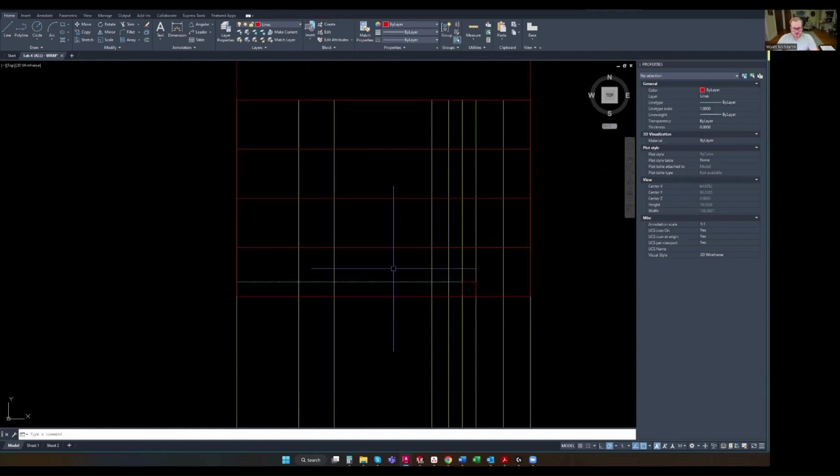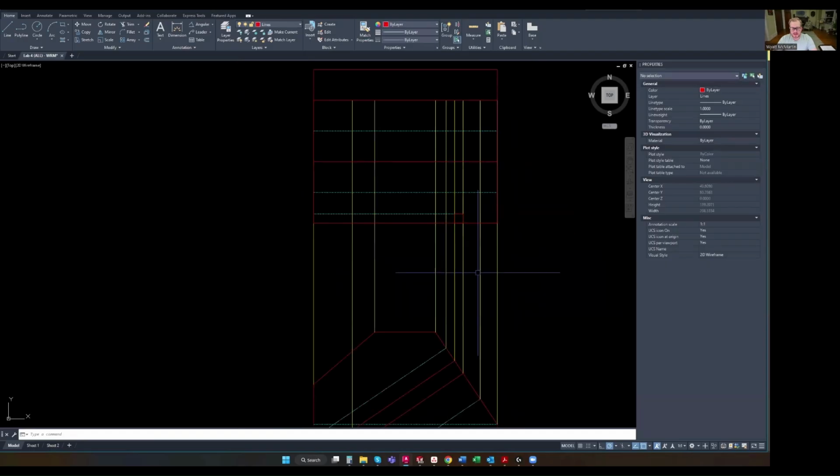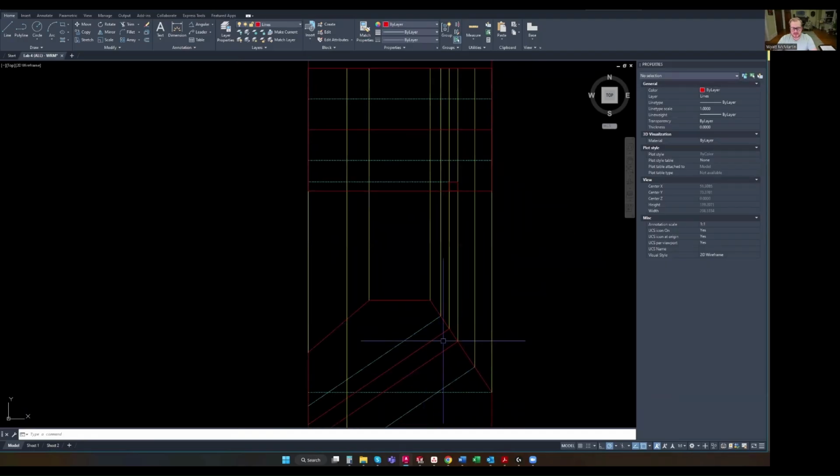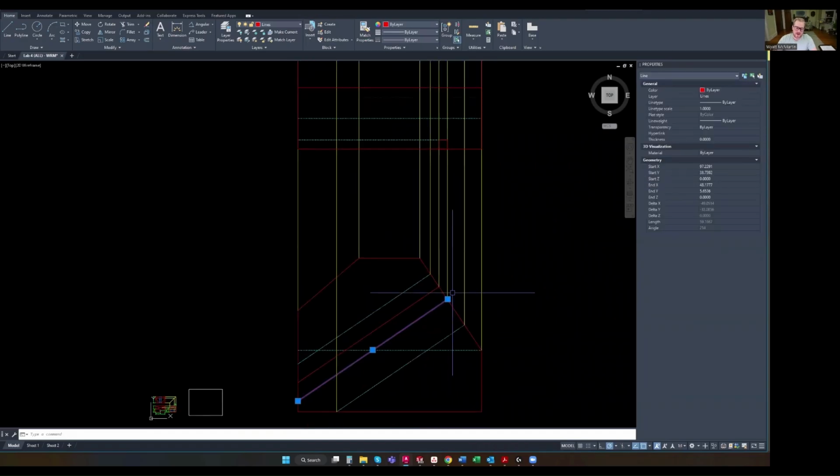There are 2 other hidden lines in this view, and they are also going to be for the cut. It's going to be this horizontal line, which would be the second of our offset lines, and our third one. Those 2 are both going to be hidden, and those hidden lines are going to stop where the center of this cutout is. The center of this cutout happens to be what's called collinear with the bottom of this slot. So this is actually going to be the center line for this hole.